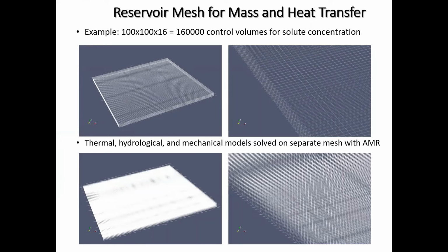And in our code, we have automatic mesh refinement enabled so that the cells that are experiencing the greatest reaction will decompose into smaller cells, right? Or cells that are very far away will coalesce. Okay, so mesh refinement is enabled.